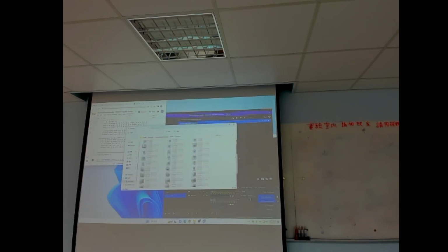So first you have to put a Z axis on every joint. If I have a joint, I should put the Z axis along the rotation axis, always in the rotation center.